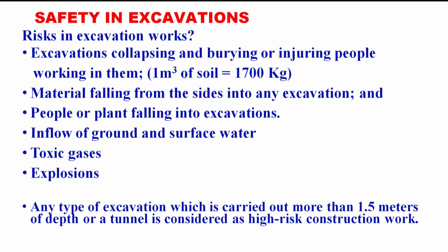Then next is the inflow of ground and surface water. There is a possibility that some source of water is nearby our excavation, or that the water table is very high. During excavation, if we hit that water table, water may come out suddenly, and because of that flooding may occur. If the workers are working in a deep trench and get trapped in that water, there may be serious problems for the workers.